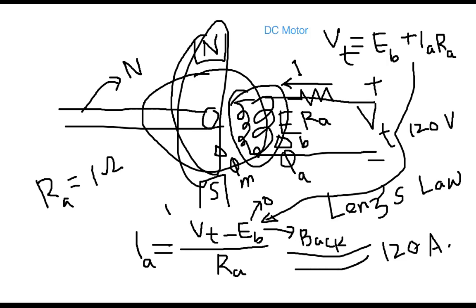So it is very rare. And then what will happen, not only your equipment issue that you don't have the ammeter to measure, these coils will be burnt. If you just apply the 120 volt and the motor is not running and the back voltage is 0, then according to this equation, because a high value of current will flow through the coils, these coils may be burnt up immediately. So that's why you have to insert a resistance.